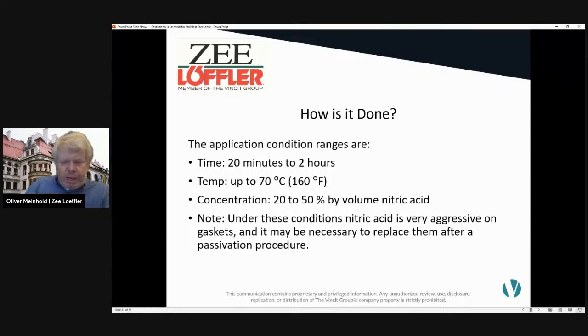And the passivation solution doesn't really change much in its concentration, so you can use the same batch for the first tank, second tank, third tank. What I would still recommend, between switching from one tank to the other, ideally, if you have an empty tote or drum, depending on the volume, is to store it in there. Don't let it sit on your gaskets inside of a fermenter, for example. And also check the concentration, just so that you have an idea how much you lost, so you can spike it up a little bit, going back to your target concentration. And then you can move on.